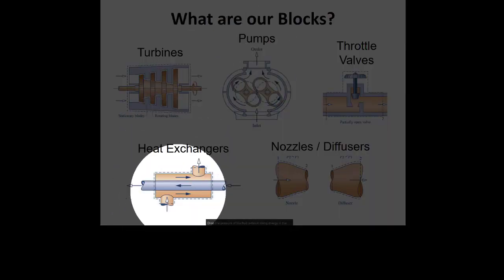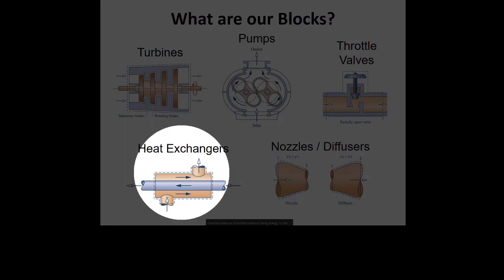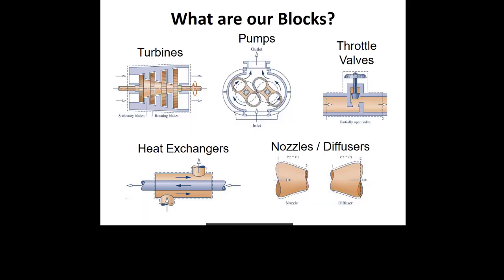We have heat exchangers. Heat exchangers are really important components. You can think about something like the radiator in your car. I don't know if you've ever seen a radiator that's behind sort of the grill on your car, but basically it's got some tubes that are carrying radiator fluid, and then it's got some fins, right, to increase the surface area. So you're trying to cool off that radiator fluid as it moves through the radiator.